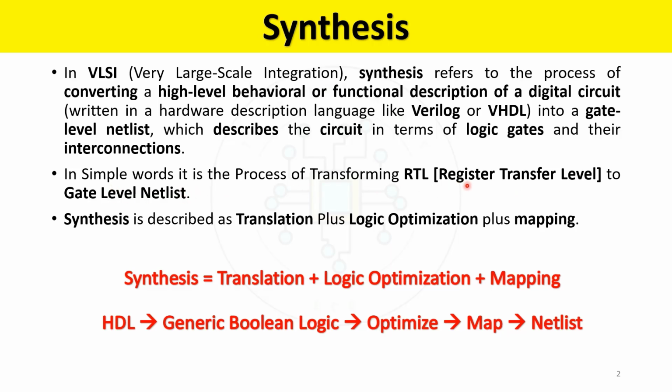Here, RTL stands for register transfer level. Synthesis is described as translation plus logic optimization plus mapping. So, that's what I have mentioned it here. And it involves these steps. Initially, the HDL, hardware description language, gets converted into generic Boolean logic. After that, some sort of optimization will happen, and again mapping will be happening. And once mapping is done, again optimization will happen, and again we get final gate-level netlist.